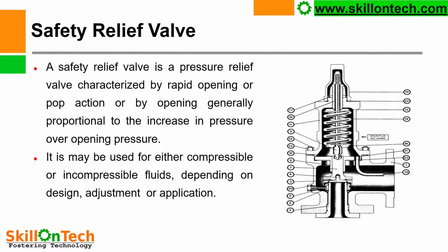Safety relief valve. You can see a picture of a safety relief valve and its internal components. A safety relief valve is a pressure relief valve characterized by rapid opening or pop action, or by opening generally proportional to the increase in pressure over opening pressure.